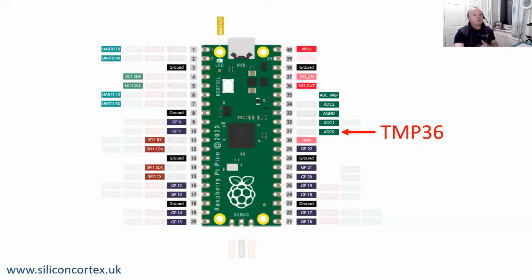And for those who meant to join us last time, this pin mapping here is what I've worked out will enable you to have a GPIO bus of 8 bits, an SPI bus, an I2C bus, analog pins, and 2 UARTs. And if you follow that regime, you can still plug in things like the displays that you can buy from the Raspberry Pi shop. We spoke about this last time. Of course, I can't get the thing out of the bag, so I won't bother.